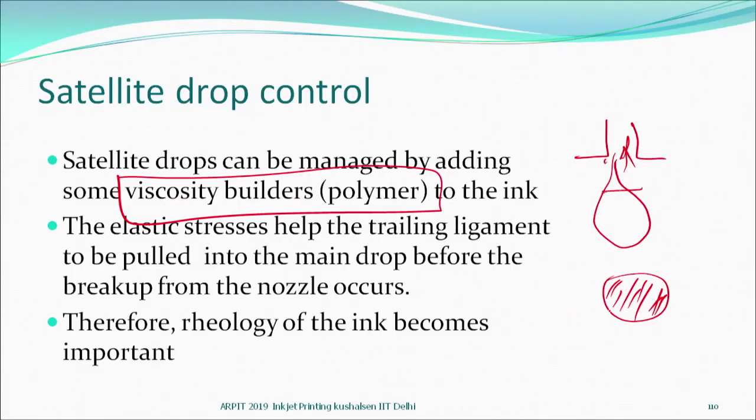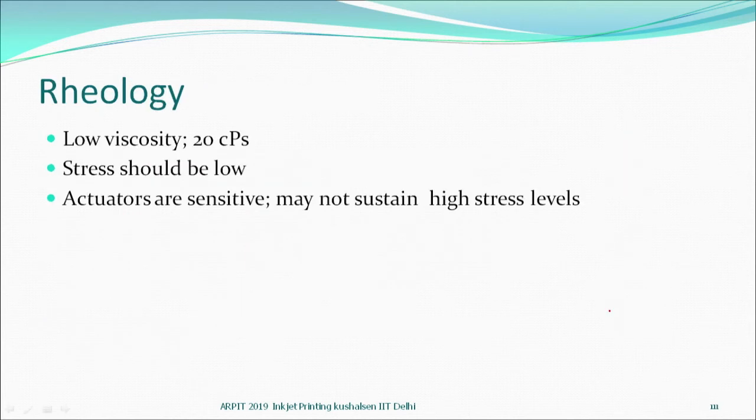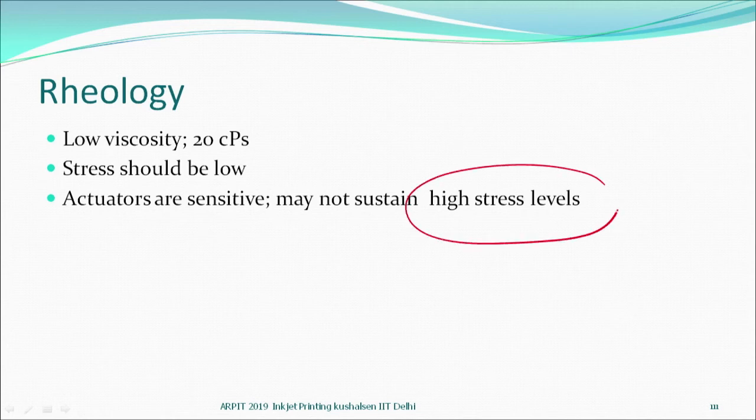So, the rheology again becomes important. So, you not only do the fluid dynamics and do the numbers, then you got to study the rheology also, control the rheology. Viscosity is low, stress should be low, actuators are very sensitive, may not be able to sustain high stress level. This has to be always remembered, but you still may have to modify the rheology.